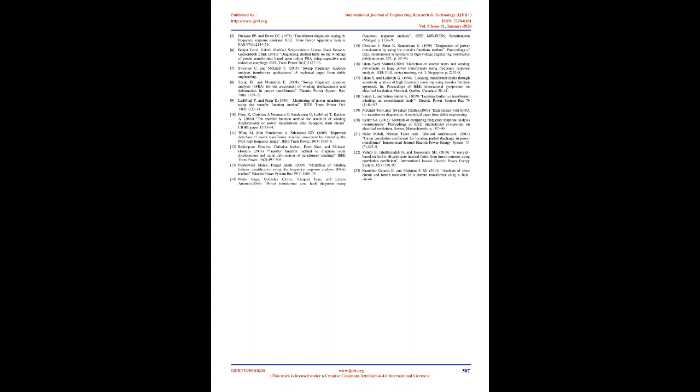As seen, the use of statistical coefficients of the SFRA records provides a quantitative way for diagnosing the presence of a fault, complementing the qualitative approaches. In addition to the benefits gained from adding more objectivity and transparency to interpretation of the SFRA results, significant advantages would accrue by quantifying the fault severity level through the use of coefficients. The results in Table 4 illustrate how the spectrum deviation of the faulty responses with the baseline measurement increases with increasing fault severity in the shorted turns.